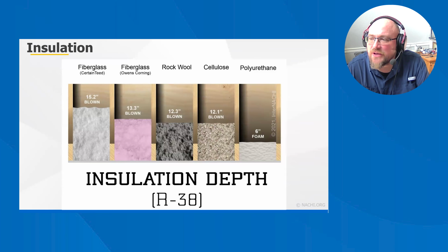Insulation's resistance to heat flow is measured or rated in terms of thermal resistance, better known as R value. The higher the R value, the greater the insulating effectiveness. The R value depends on the type of insulation, which includes its material, thickness, and density. The effectiveness also depends on how and where the insulation is installed. For example, insulation that is compressed will not provide its full rated R value.